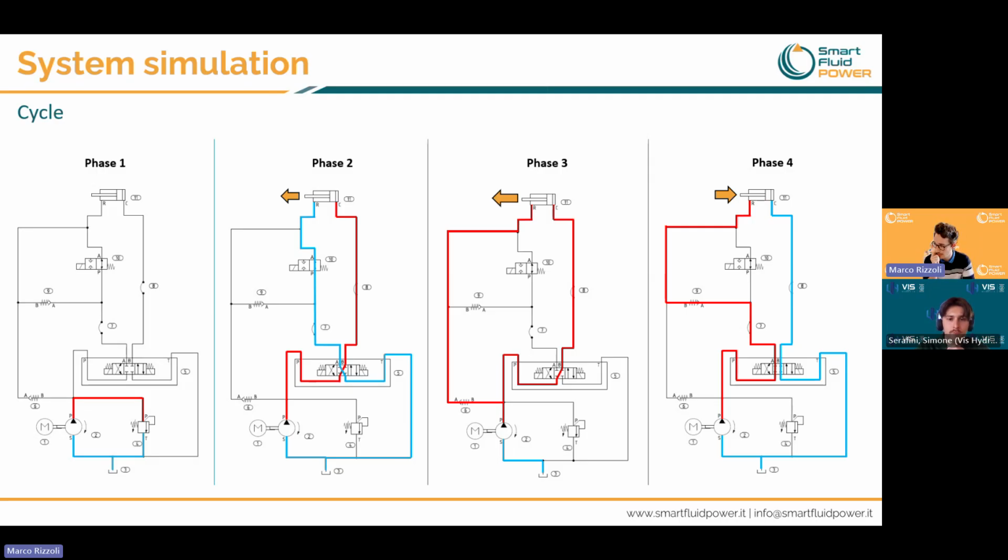Activating the speed valve, we have the closing of this line, and we command the returning oil to communicate with the power line through a check valve. And this allows us to multiply the flow rate that reaches the head side of the cylinder, even if we have a limit in the pump generation.